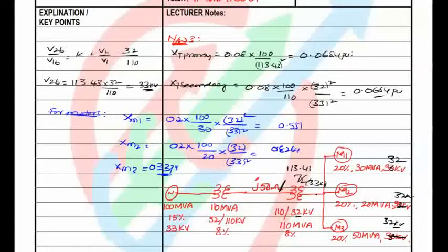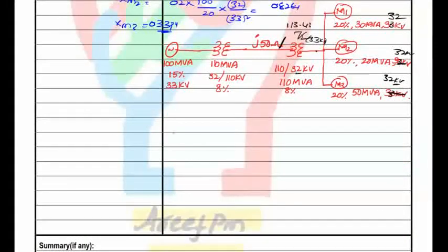Okay, so we'll draw the single line diagram here. In the previous session, we discussed how to draw the single line diagram for various equipment such as transformers, transmission lines, and motors. So according to that, we will draw it. The alternator can be represented as a voltage source. It is represented as EG here. By default it is a 1 per unit value, and we are going to specify its reactance. What is the new reactance? The X per unit new value is 0.15. It is nothing but XT double dash. So this part is completed for the alternator.